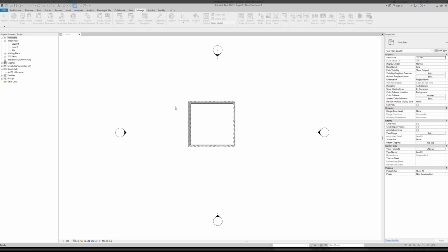But Revit doesn't have a phase called demolition or temporary. Those are not phases, those are actually time period conditions. So you will either have something which already exists in Existing, and you are going to build something in New Construction. So there will be two phases.